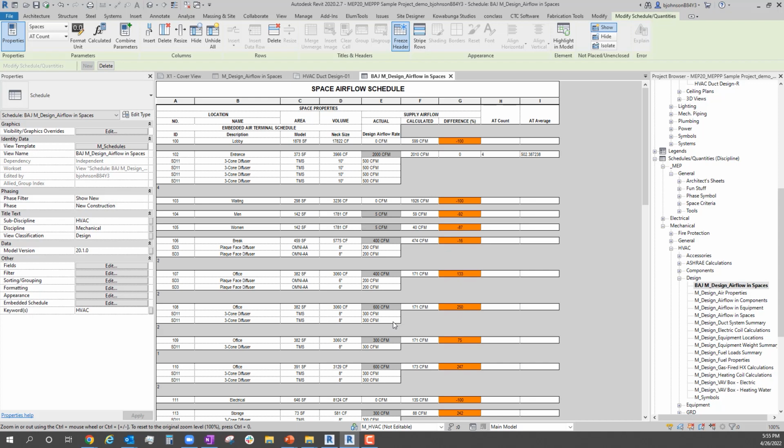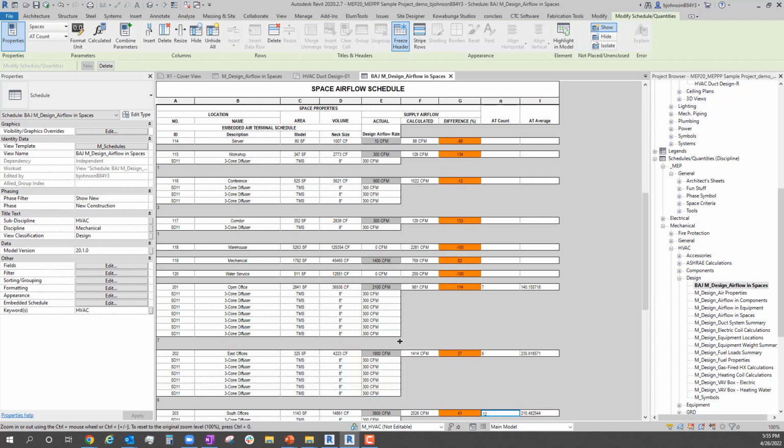Before you even leave the room, most people that I know as designers will give it a CFM value on what they think it should be. Doesn't matter if they've done any calcs or not. Doesn't matter if they've run heating and cooling loads or not. They'll just say, I think this space requires about this. And that's where we get numbers like I saw down here, where 300s were twice as much as potentially they should be, by 140. So I come in here and make all those 150s. Again, I'm probably more than 5% at that point, probably upwards of 6 or 7%, something like that. So it's still going to be orange, but at least I used the buffer that I really wanted in that case.